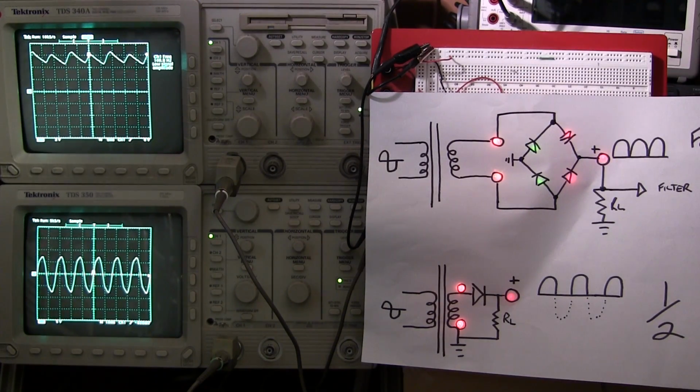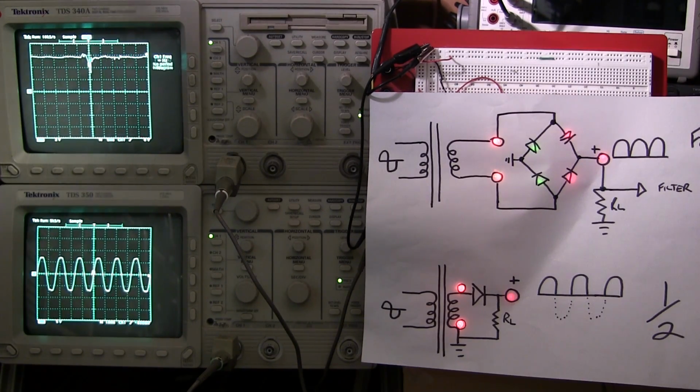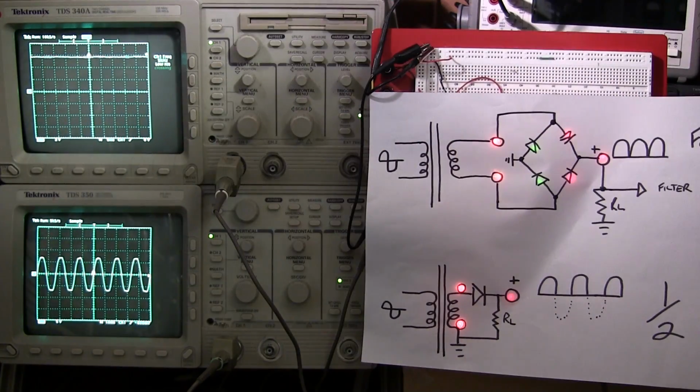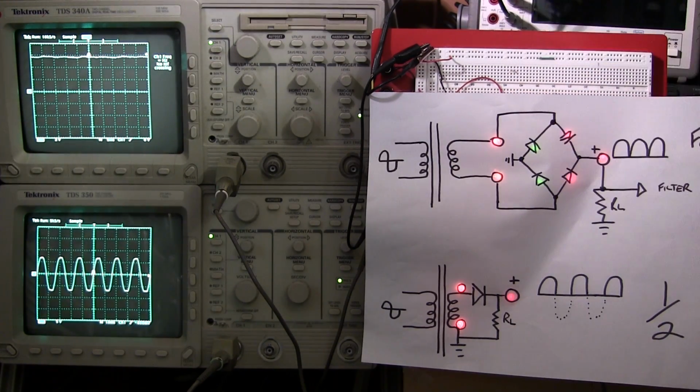All right, so what I'll do is I'll add a different capacitor here. I'll add this 330 microfarad capacitor. As you can see, we're getting pretty close to being filtered, but you can see there's still a little bit of movement there. So if I load this, we're definitely going to see some ripple because this is going to discharge that capacitor. So really what I'm going to do is put a heavier load across this. I'll just put that on here. And as you can see, we get quite a bit of ripple because it's just loading it so hard.